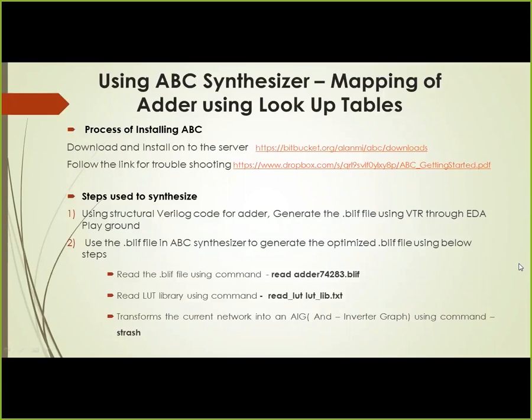These are the steps to synthesize. We get the Verilog code which the professor sent us. Then we convert the Verilog code to a BLIF file using EDA Playground. We use the BLIF file in the ABC synthesizer to generate the optimized BLIF file using the steps below.